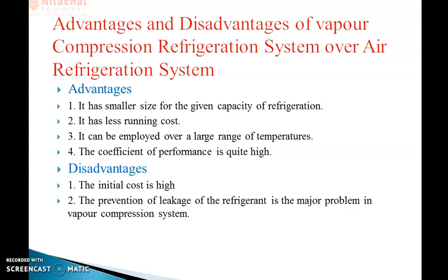So you observe that ammonia has a higher heat capacity than air. The heat carrying capacity of air is 1, but the ammonia heat capacity is 2.175 in gas form. So it will carry more heat, so that your coefficient of performance will increase, because the coefficient of performance is directly proportional to the refrigerating effect.